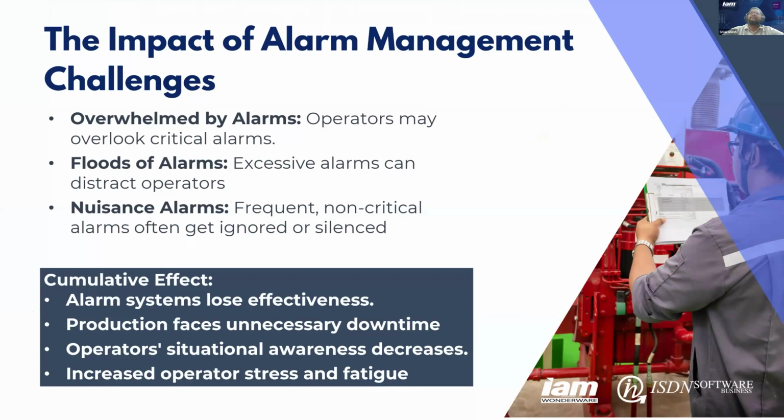Immediately in your alarm screen, 30 alarms will pop up. The operator will tend to miss one of them, which could be a critical alarm that you need to pay more attention to. But because the alarms come in a huge bulk, the operator tends to miss the key or important alarm.